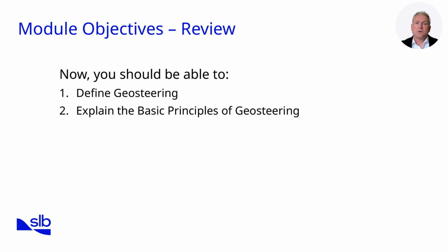We did this by walking through the workflow, building geological and property models, generating forward logs, matching real-time data, and updating models continuously. The third objective was to review geosteering methods. We compared model compare update, dip determination, and distance to boundary, highlighting the strengths and limitations of each.